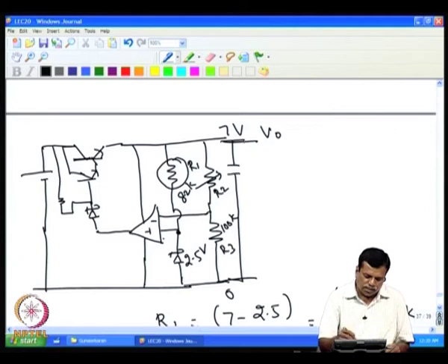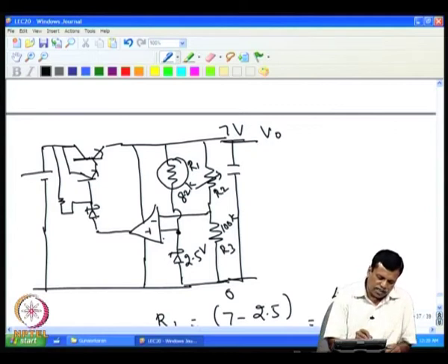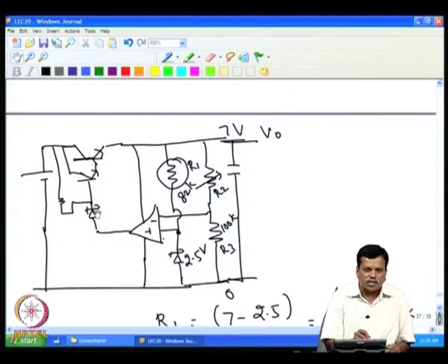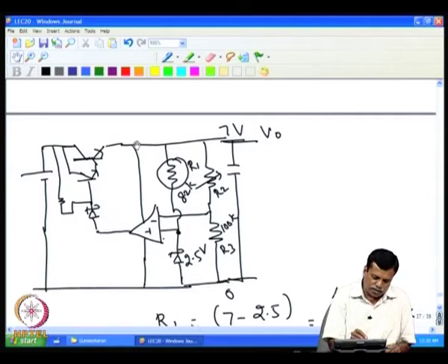So you will get a regulated voltage as we explained earlier, and this zener is used because the circuit has to start initially, and initially the voltage here is 0. If 0 voltage is there, the op amp is not going to work. To make the circuit work, we have biased this using this. So we have put, for example, a high resistance here, say 470k.